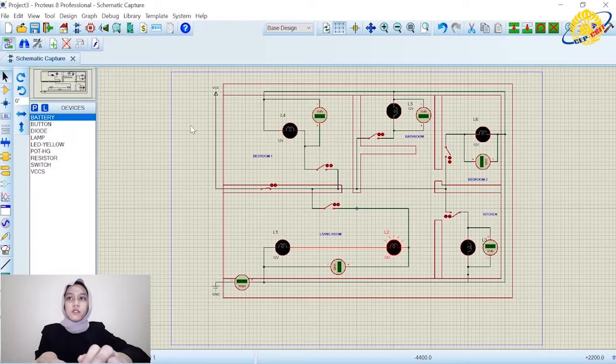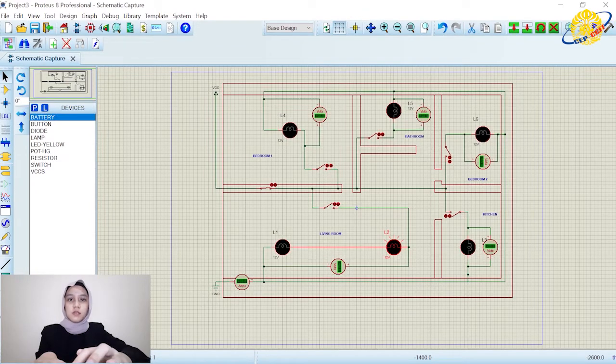Terminals are used for specifying the interface to a circuit. Both ends must connect to something, so all the inputs and outputs in our design will be indicated by terminals. We use power and ground. These are the power rails that are connected to hidden pins.